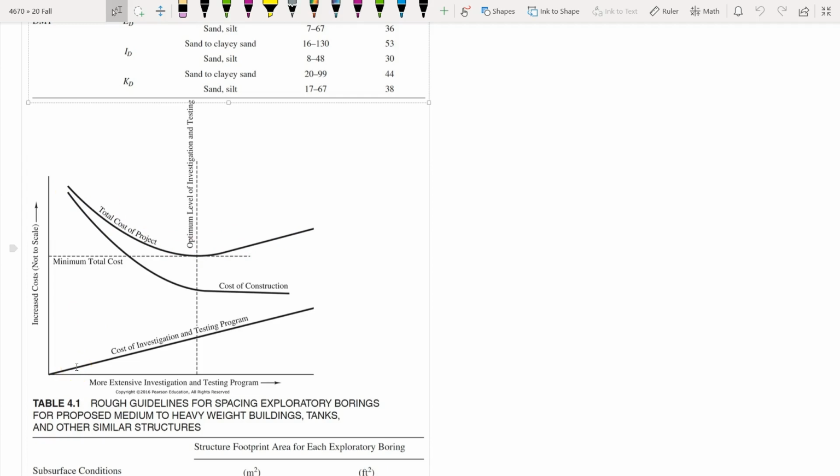investigations, which means you don't have much field tests, CPT, SPT, or laboratory tests, you are bearing high uncertainty on your soil properties. So either you need a very large factor of safety for design, or you suffer from errors in calculations or estimations of the soil properties.